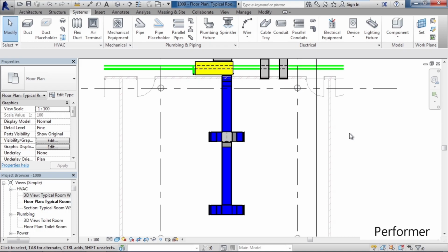Other options we saw were the different solutions at which Revit calculated this layout for the duct work, from the actual component that's supplying the air to the actual diffusers. We chose the solution 4 as the result we would like automatically created. Last step was to automatically create this, and then we looked at the actual model in 3D.